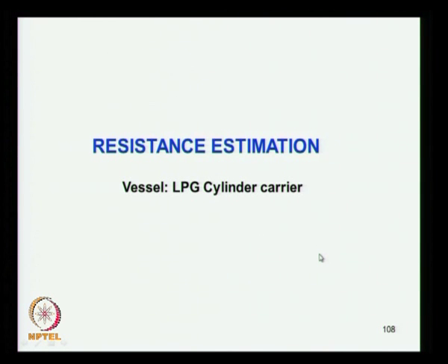So there are different other methods, maybe some of the resistance calculation methods for advanced vehicles, high speed vehicles and maybe catamarans, so we will be discussing later. These are generally meant mainly for displacement type vessels, the methods we discussed, Holtrop-Mennen method, then Funk's method, Guldhammer-Harvald method, all these are meant for displacement type vessels, even including the Mercier-Savitsky method. It can be applied to planing vessels, but only for the cases when it is in the displacement mode.